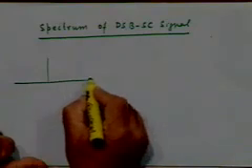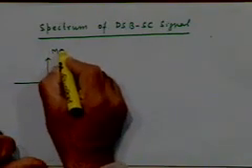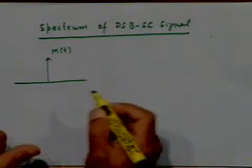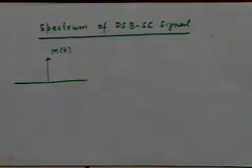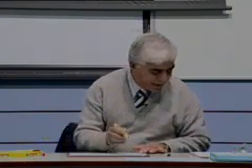To discuss this, let's assume that your message has some spectrum, and for the sake of these discussions I'll typically assume the spectrum to be real valued, so that I don't have to carry out two plots, one for the amplitude and the other for the phase. But it is implied that if required one can do that. Whatever we do for the amplitude plots will also be valid for phase plots. For convenience we will take the spectrum to be real itself, so M(f) directly completely describes the spectrum.